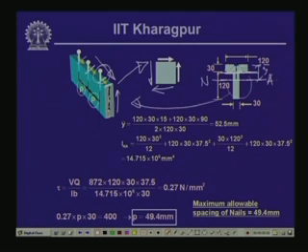The first segment is 120 by 30, so 120 times 30 times 15 is the moment of that area with respect to the top line, plus the area of the bottom part, which is 120 times 30 times 90 (60 plus 30), divided by the area of the whole cross section, which is 120 times 30 plus 120 times 30. This gives us a value of y bar equal to 52.5 millimeter from the top.